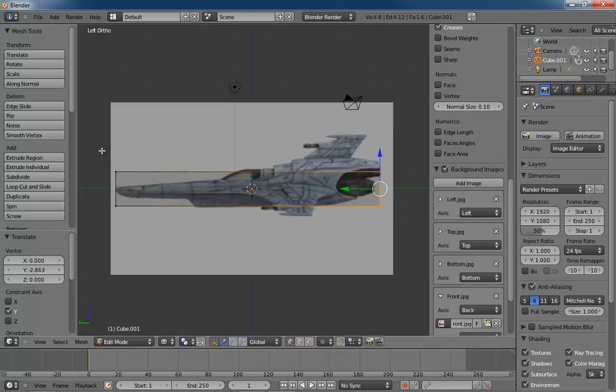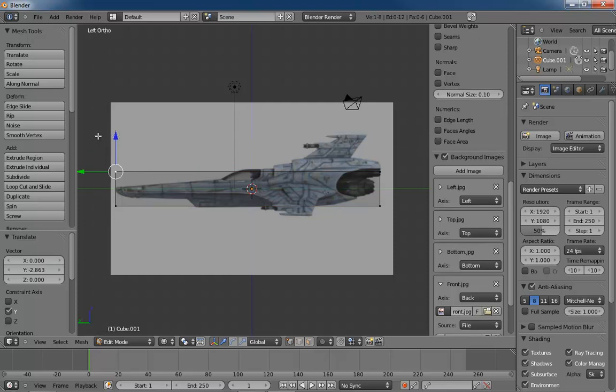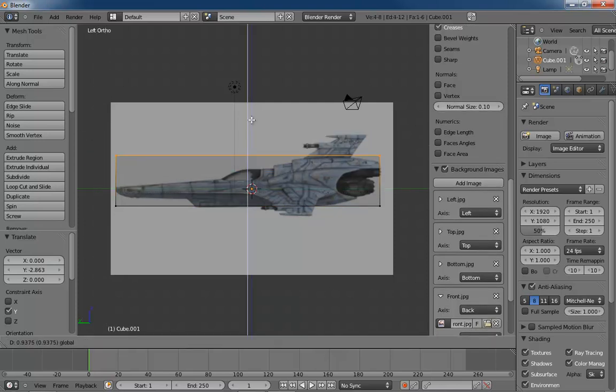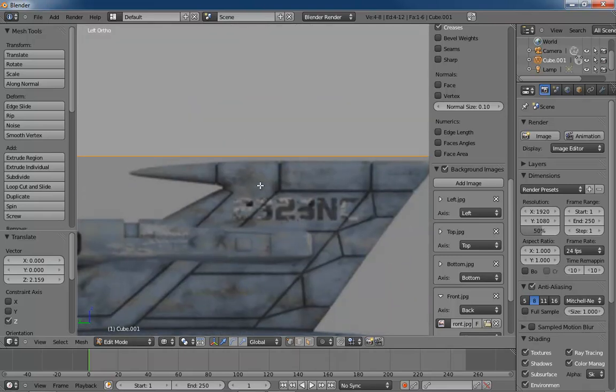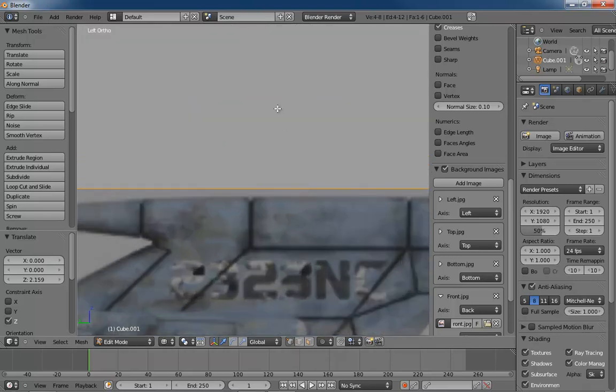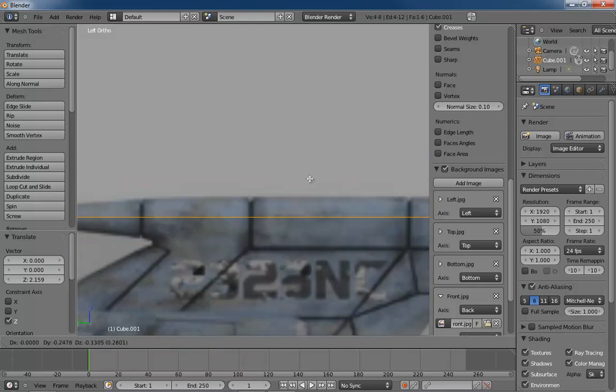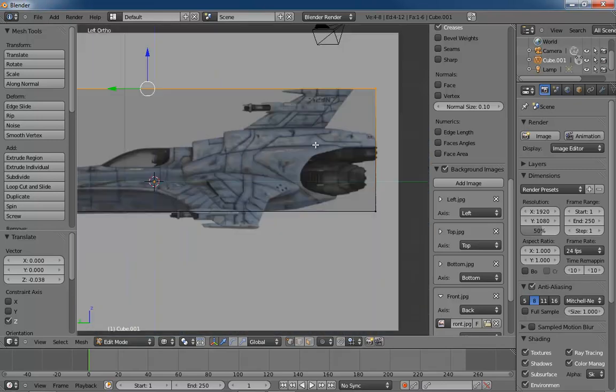because what I'm going to do is click out in space again, hit B once more, and grab all the vertices here at the top, and place them such that they are sitting right on top of this guy here. And I can just drag with the mouse. Now, in this dragging operation, I'm moving in all three axes, well, two axes anyway, and I don't necessarily want to do that. So I'm going to tap the Z key, so now I'm only moving along Z, and I'm just going to place that right on top, like so. And as soon as I'm done, click, and we're good to go. With a little more thunder, just for dramatic effect.